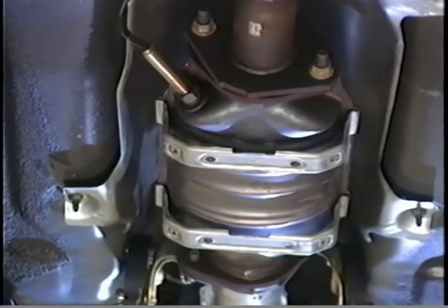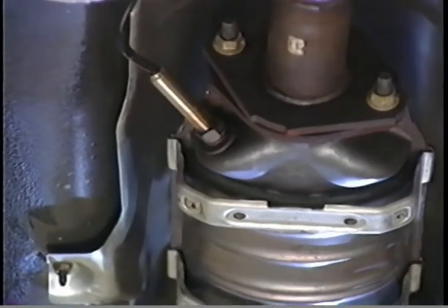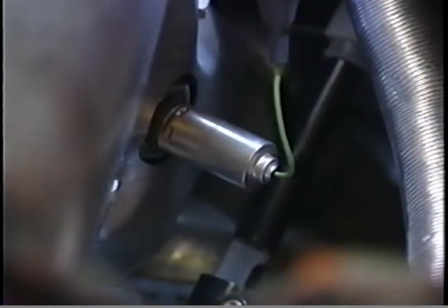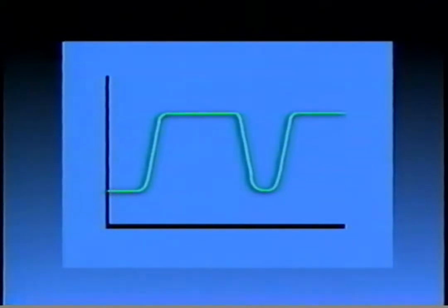To make this determination, the ECM compared data from the rear O2 sensor to that of the front O2 sensor. During normal operation, the voltage value for the front O2 sensor rapidly changes from negative to positive, indicating the front sensor is constantly adjusting the air-fuel ratio. If the catalytic converter is functioning properly, the voltage value of the rear O2 sensor should change slowly, which indicates the exhaust gases are being treated as they pass through the converter. These voltage change rates are called the switching frequencies.